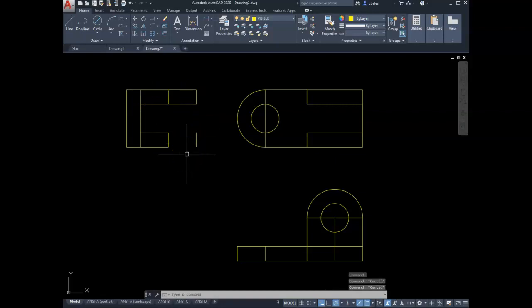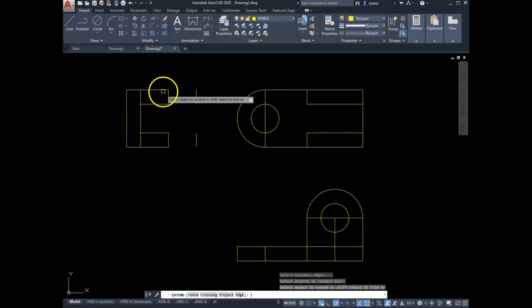It's hard for me to explain why that's not good. It can make it difficult for finding edges, finding snap points. It can make it difficult for finding lines under lines, when you have lines on top of lines. It can make it difficult for continuity, right? We want to have one line, but instead we break it up. So maybe there's a problem with that midpoint. So if at all possible, you want to extend these lines to make them continuous.